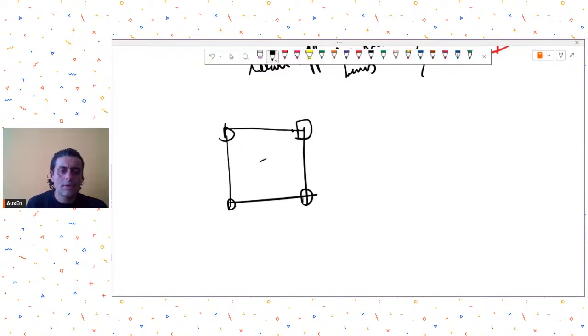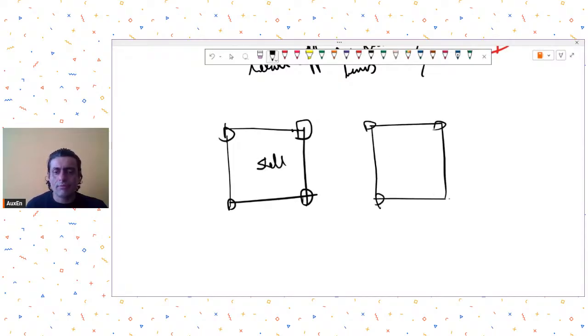Let's say I have modeled it as a shell, and then I model the same geometry as a membrane, and you will see right now that the aspect ratio is almost close to 1. So in membrane the load distribution will be on the basis of tributary area.